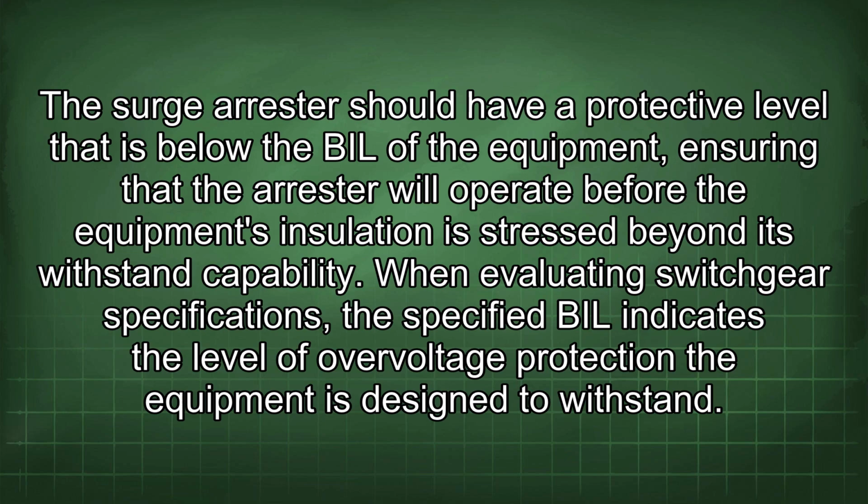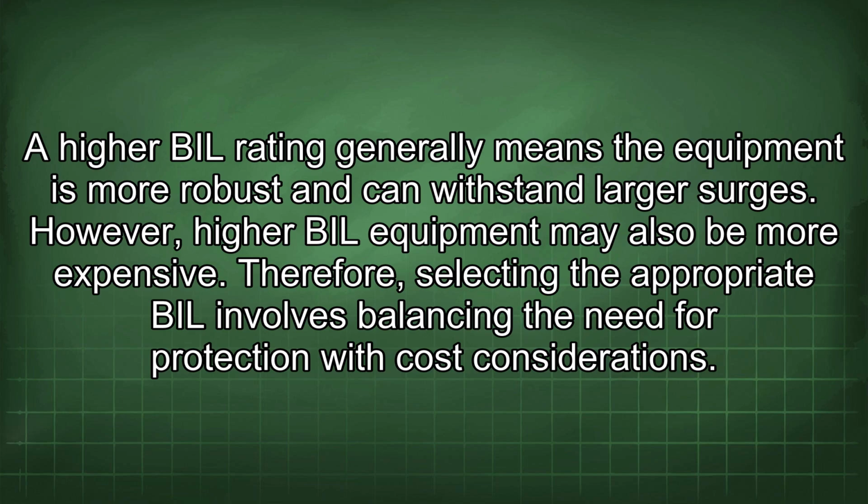When evaluating switchgear specifications, the specified BIL indicates the level of overvoltage protection the equipment is designed to withstand. A higher BIL rating generally means the equipment is more robust and can withstand larger surges. However, higher BIL equipment may also be more expensive. Therefore, selecting the appropriate BIL involves balancing the need for protection with cost considerations.